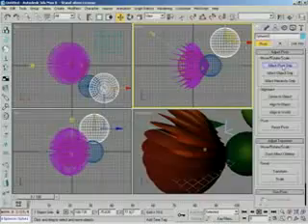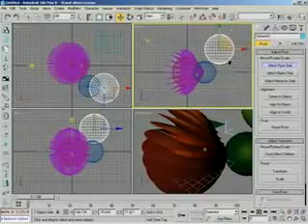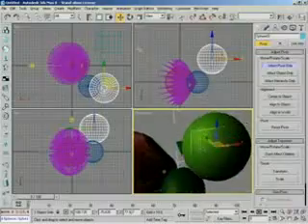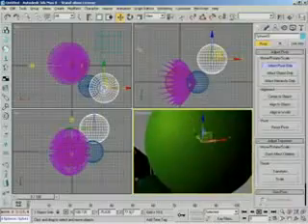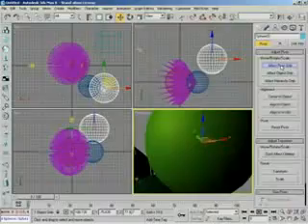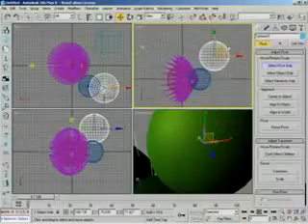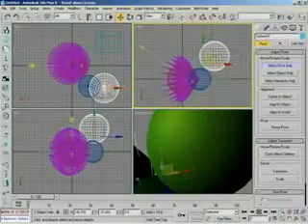Give us some examples. Let's click Affect Pivot Only. Notice that our transformation gizmo has changed a little bit. Yeah, it has a green box, a fancier thing. These extra, big, blocky thick arrows on here. I'll just unclick that. See how it's gone? Now it's back. Very cool. What does that allow us to do? This allows us to move our pivot, or relocate it.